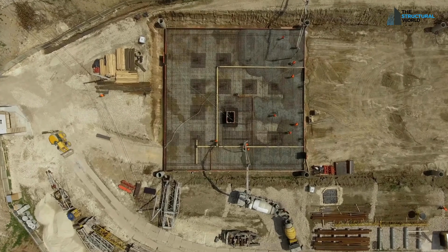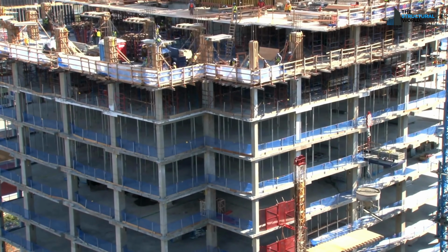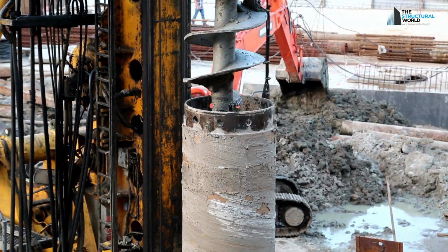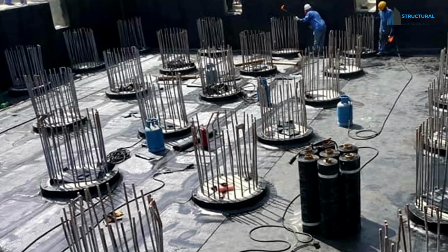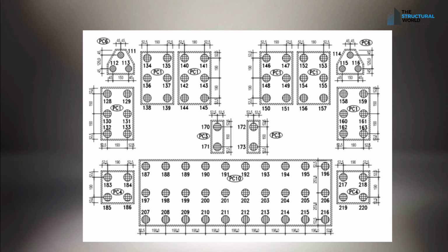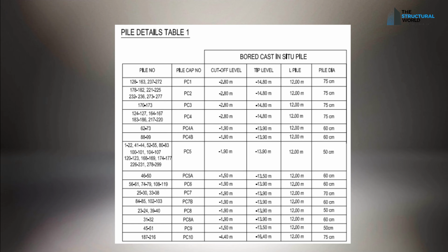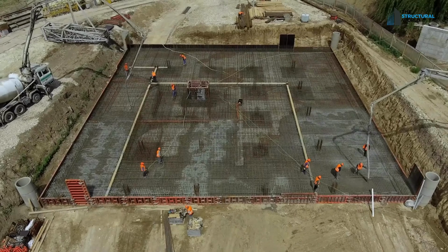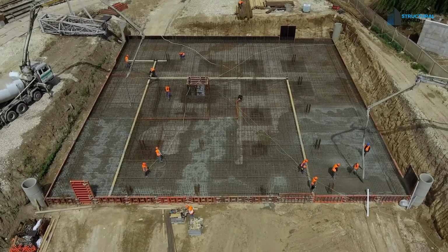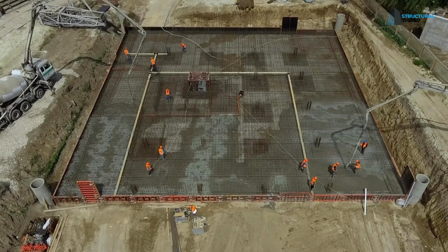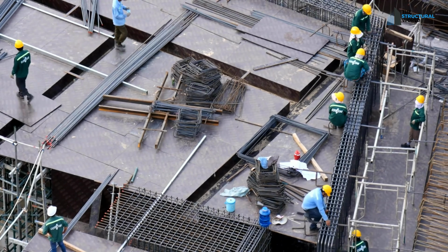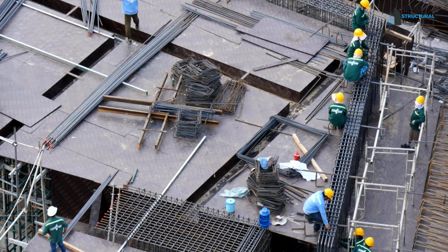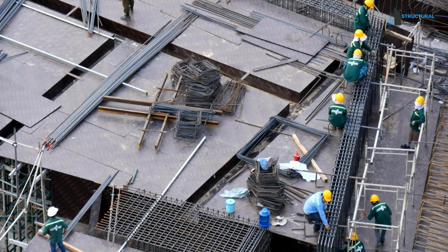Especially for bigger projects, we will encounter the types of pile foundation, for example. The same as isolated, pile foundation can also be distinguished by tagging the type of pile or pile cap, and a corresponding table of schedule will dictate the dimensions, thickness, and reinforcement required. Except for those of raft or mat foundation, reading the number of reinforcements and thickness and how it will lay at site is similar to reading a suspended slab, which will be discussed shortly.